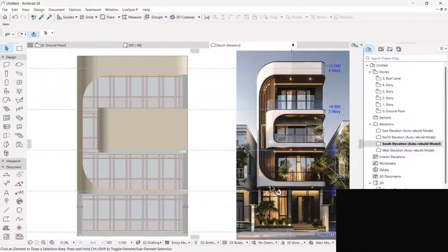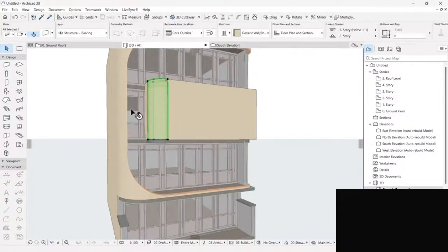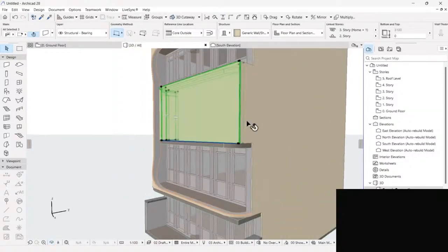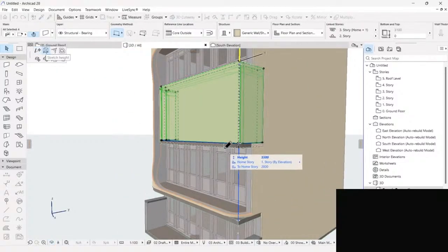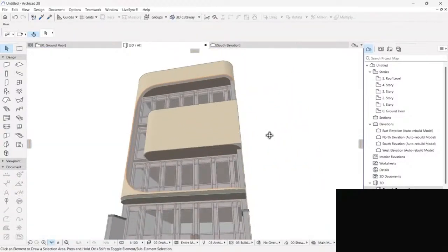You see the walls are covering our slabs, the extent of our slabs, so we need to try achieve that as well. So I might select these ones like that and stretch them from the bottom to align them with the bottom of our slab, like so.